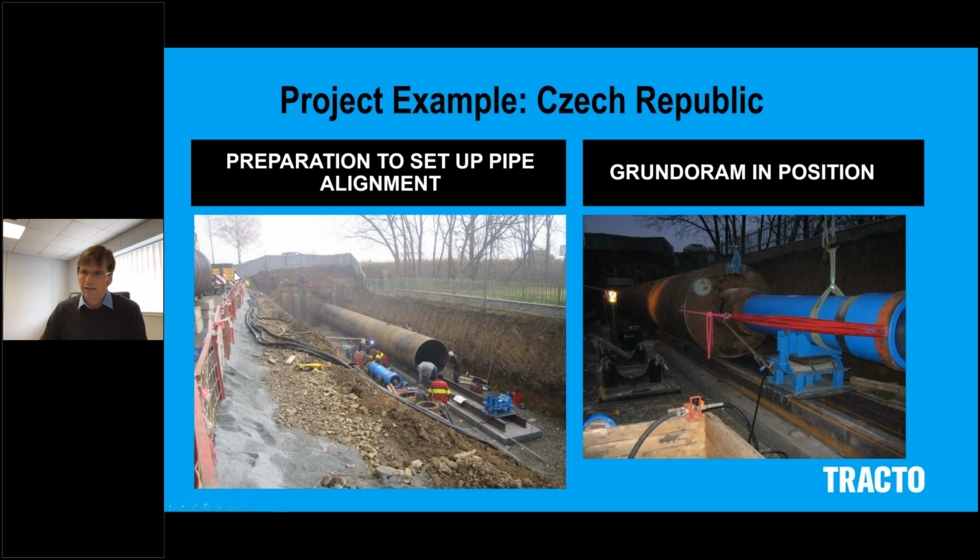There's actually 3 large compressors on site. You see here the 3 air hoses. So ramming requires large volumes of air. And also here on site, I don't know whether you can see my cursor, is the ram cones and all the various pieces of equipment. In the right-hand side picture, we see the cotter segments in place and the ram cone actually installed.